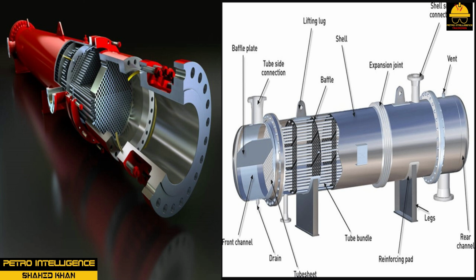or U-tube. On a fixed head heat exchanger, as shown in the picture, tube sheets are attached to the shell. Fixed head heat exchangers are designed to handle temperature differentials up to 200 degrees Fahrenheit or 93.33 degrees Celsius. Thermal expansion prevents a fixed head heat exchanger from exceeding this differential temperature. It is best suited for condenser or heater operations.